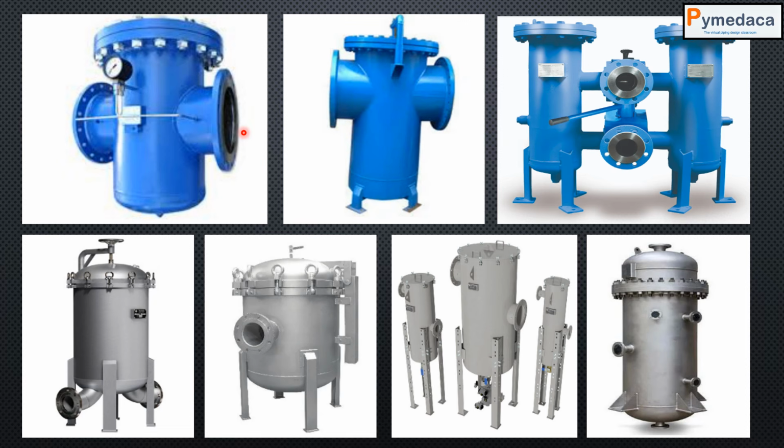It will have an inlet, it will have an outlet. Whatever items are inside, it's going to filter out. There are filters that come with supports. There are skirt supports, leg supports, and different types of supports available. There will be different sizes of nozzles, different orientations of the nozzles, level gauges, and those things. But technically the intention of the filter is to do filtration of the hydrocarbon, as planned and designed by the process teams. These are dual filters, which do much higher filtration compared to the other filters.